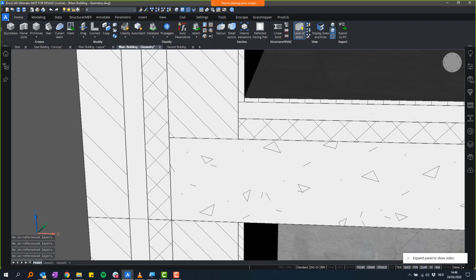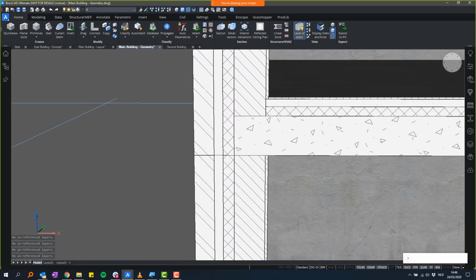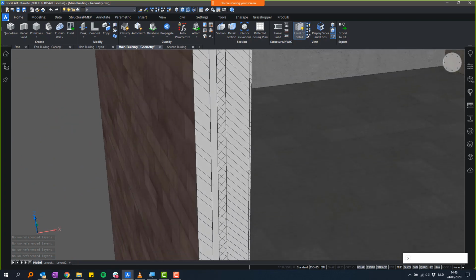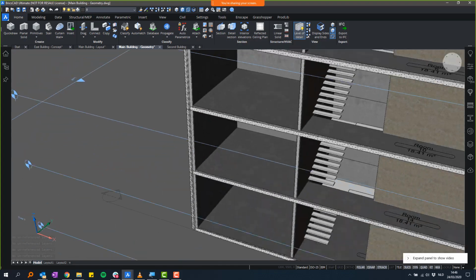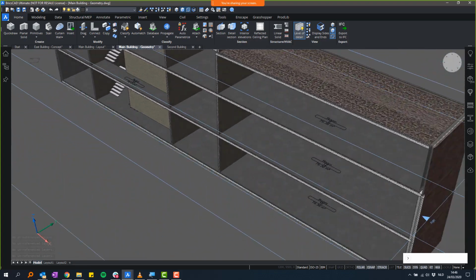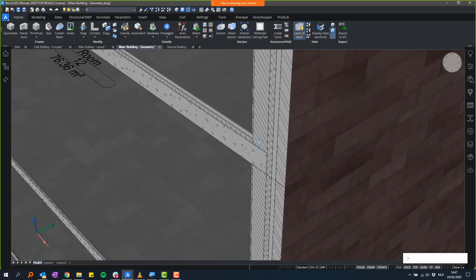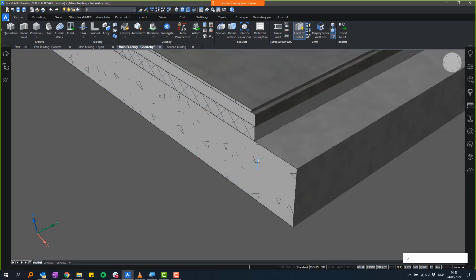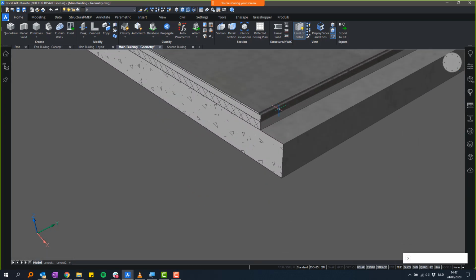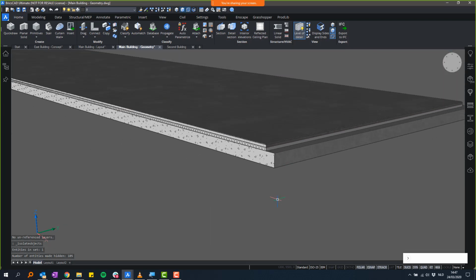And you'll see now that this connection has also been applied, for instance, here and here. So in the entire drawing, basically. Which is obviously very important for things like your quantity takeoffs, because now we have the exact quantities for everything. So like for the concrete of the slab, which has a different area than the tiling, you need to know this, of course. All of this information can be extracted, of course.